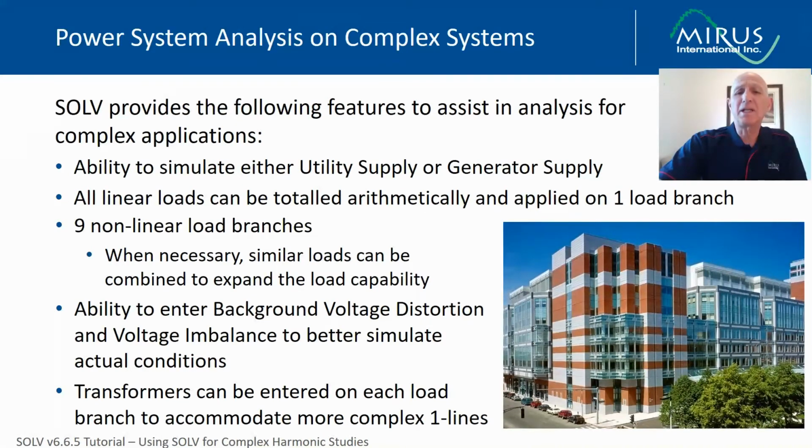SOLV is uniquely equipped with the ability to enter background voltage distortion and voltage imbalance to better simulate actual conditions. And transformers can be entered on each load branch to accommodate more complex one lines.